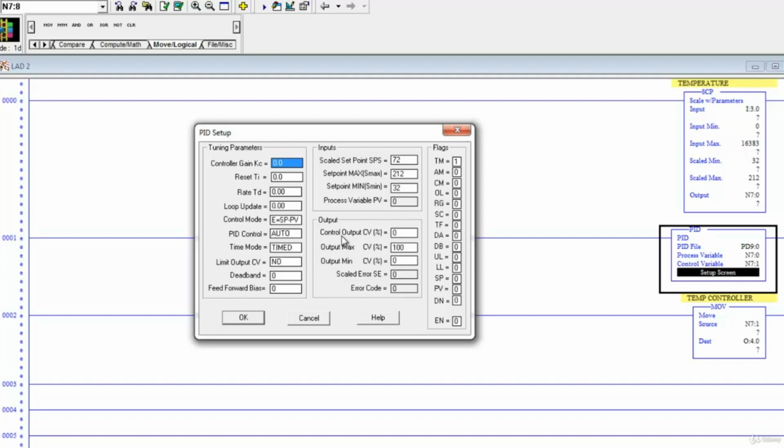Assuming that we're up, we're running, we're connected to our heater, and we're receiving input from our temp sensor, we want to let the system run for a few minutes until we see what the process is doing. We want it to be stable. Now when I say stable, it might not be steady, but we do want it to be doing the same thing continuously.